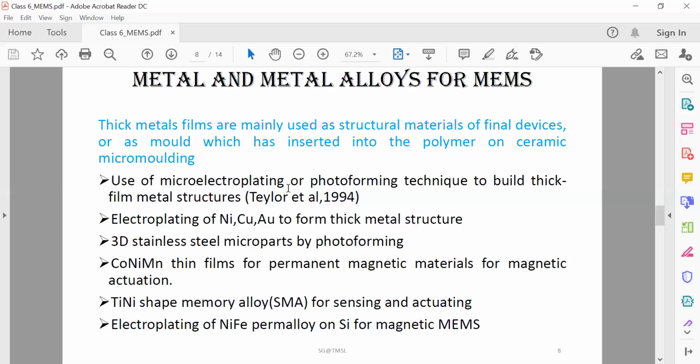Now, electroplating is getting a lot of importance nowadays, because this particular technique is a low temperature process where chemical techniques are used, and basically it is electrolysis of some chemical solution. We have to use the cathode and anode, and supply some current to that electrolytic cell so that the chemical electrolyte will decompose, and there is some part that will be the metal, and the metal will be deposited on the cathode.